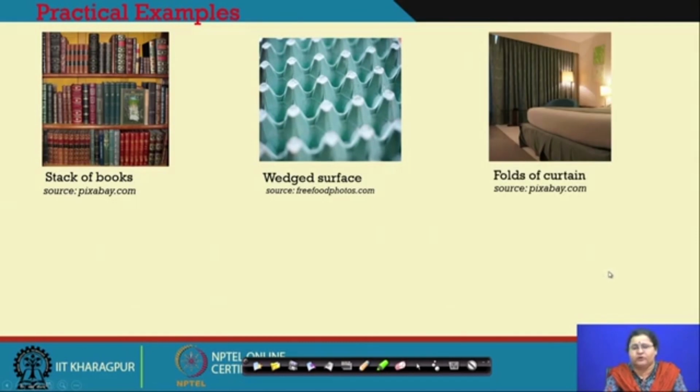You have folds of curtains. You can see in the window, you can see the curtains over there. They also do a big part of sound absorption, but they also help in the diffusion process. So, when you are inside a room, the sound comes to you after rebounding very uniformly, and that creates a live room. Otherwise, if it is reflected on and on, receivers can get glares, sound can reach them only by reflection, then it becomes an annoyance to their ears.